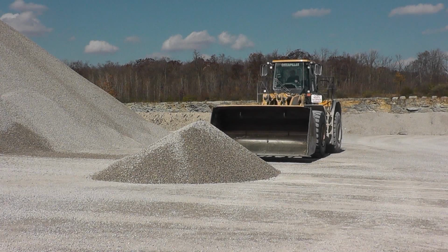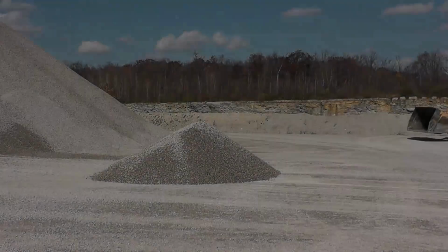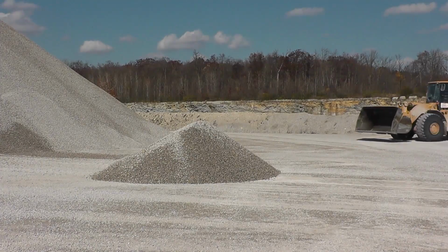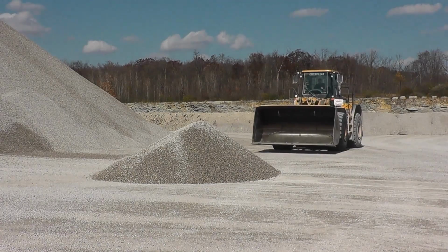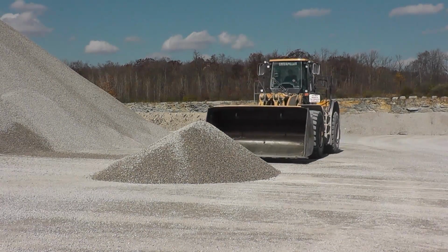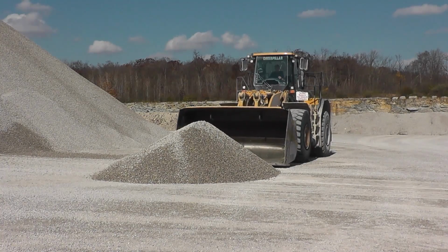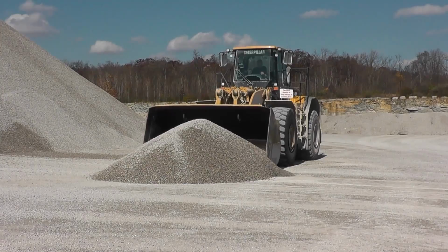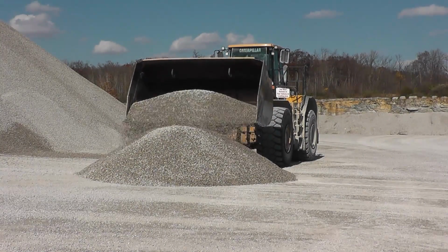Once the loader operator has laid out enough material, the next step is to thoroughly mix the sample pile. At this point, the sample pile will typically have an oblong shape. The loader operator begins the mixing process by starting at one of the ends of the oblong-shaped sample pile. The bucket is lowered to the ground but not scraping the ground, and the bucket is pushed into the sample pile until the bucket reaches the midway point of the pile. Then the bucket is slowly raised and that end of the sample pile is smoothly rolled.